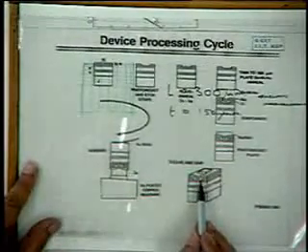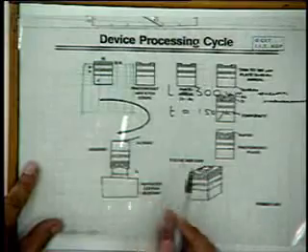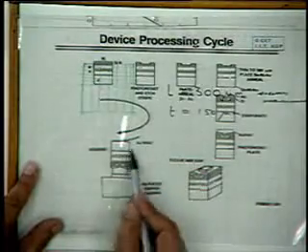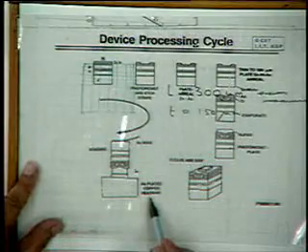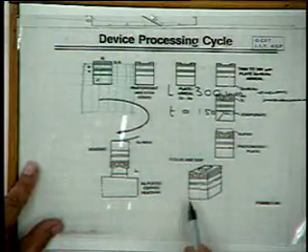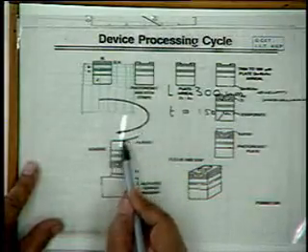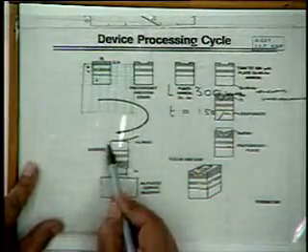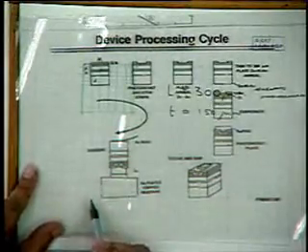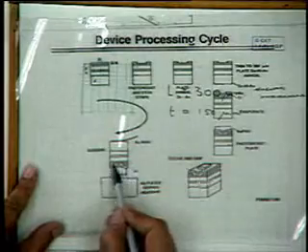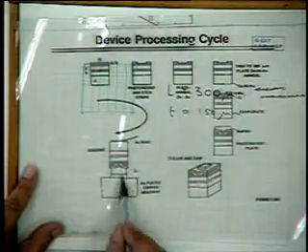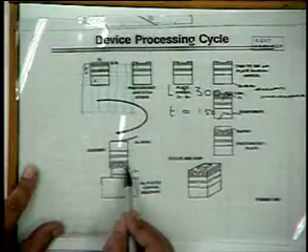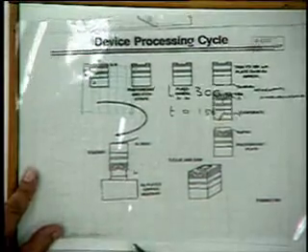What is then done is that we invert the device. This p-type side is bonded down on a gold-plated copper heatsink. Why? Because it makes for easier bonding. And also because this is a small area, whereas this is a large area, and the gold wire is bonded to the substrate side. Another advantage of this is, where is the junction? The junction is right here at the top somewhere. So the junction is much closer to the heatsink. So this is a standard geometry edge emitting device, and the light will come out from the edge of the wafer.